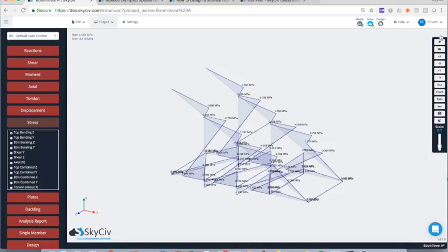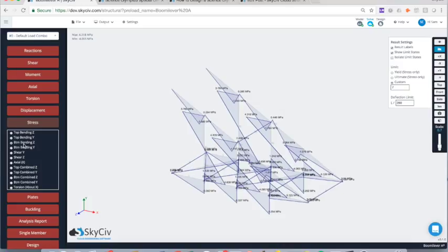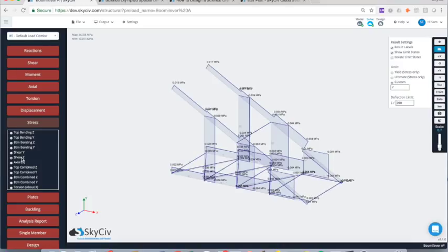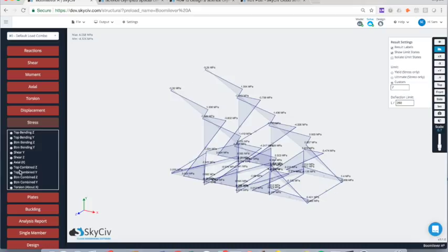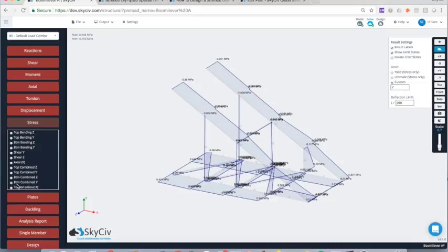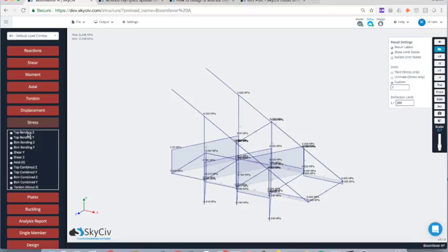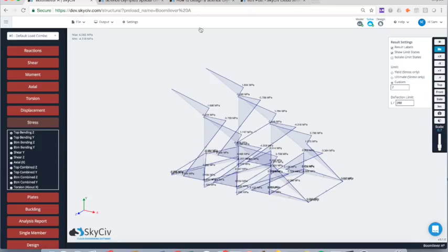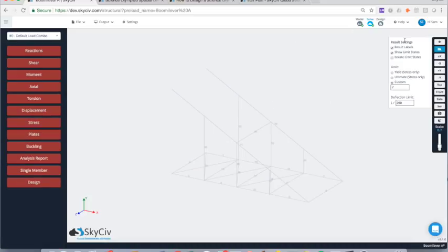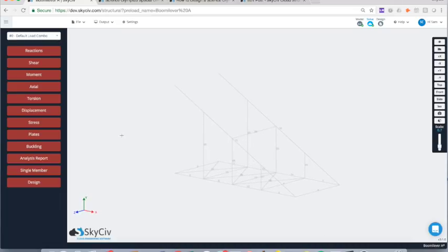Okay, so now we can see under that limit, the 7 MPa limit, and my max and mins, it seems like the bending stresses are all okay. Shear stresses are fine. And my model seems to be safe under that load that we've applied and under the limit of 7 MPa for all of our members. So this would be a design that I would see as working. And so from here what I can do is actually get the material, the structure weight as well.